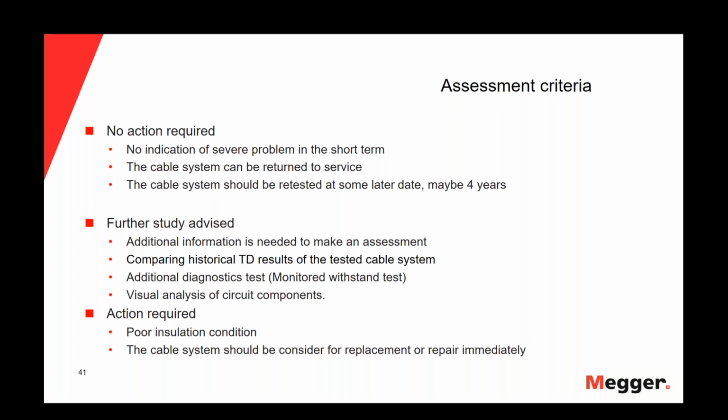It's very important to keep in mind that if we are doing a tan delta test for the first time, we will not be able to make a decision regarding that cable. If we do a tan delta test and the assessment criterion I get is action required, that doesn't mean that I need to change my cable immediately. Maybe I need to put the cable back in service and repeat the tan delta test in 1 year, and see the behavior of the tip-up, or the delta of the tan delta, and the standard deviation, to try to take a decision, but never take a decision from one first measurement of the tan delta.